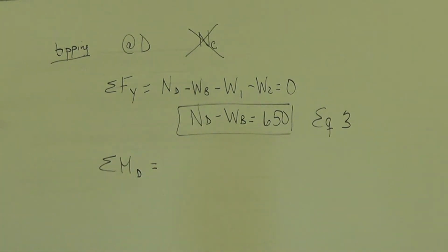Is NC, do I put NC in the equation? No. If there was a frictional force, would I put the frictional force in the equation when I sum the moments about D? No. Why not? Because the frictional force goes right through point D. It can't create a moment.